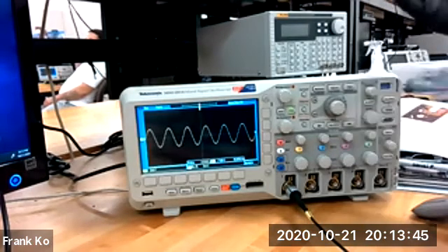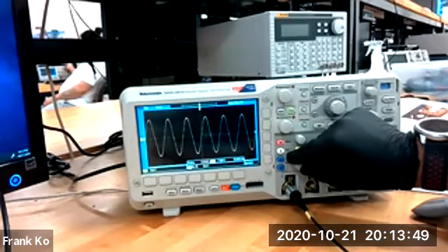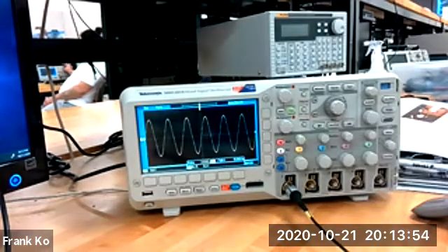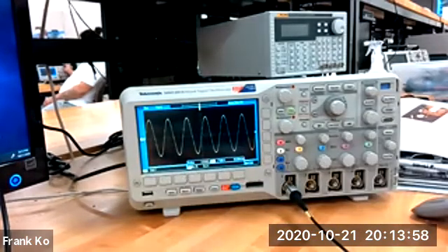20 volt, well, mine's a 20 volt peak. Can you make this waveform one? Okay, make it a little taller to fill the display screen. Is your scale now a different scale? Mine is set at 10 volts per division. What's yours set at? 10 volts per division?